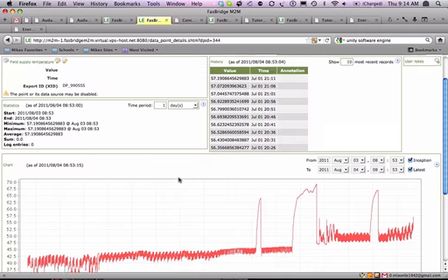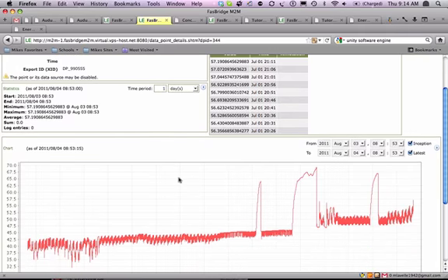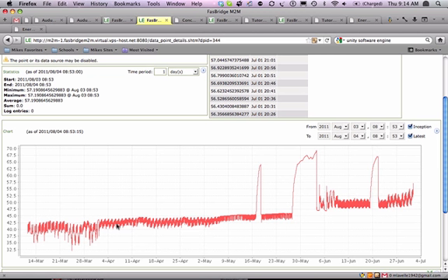Now we can also check the field supply temperature. This is the temperature going out to or being delivered back from the well field. So we're starting down in the middle of the winter at 40 degrees. We're essentially extracting heat from the ground at somewhere between 40 and 42.5 degrees. We're pulling that heat out, we're moving it up into the building. This is our source of heat in a ground source heat pump.